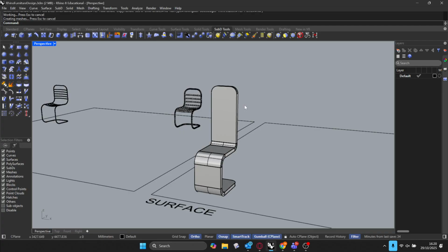Offset, I just did 5. And it'll just, it's a sheet material. Or you could do 10 if you want. So a nominal size is maybe 18, because that's the sort of thickness that sheet materials come in. So you could do 18 if you wanted to. But yeah, just find, and then if you wanted to fillet the edge, you can. So you can type fillet edge, and you can just select these back edges or the top edges, and then we can start to fillet those edges.